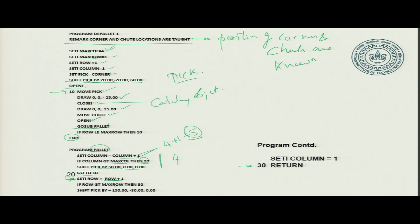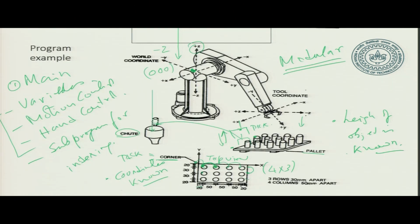Now, if the number of columns is not greater than max, then what it will do, it will shift the pick by minus 150, 30 and 0. So, from here it is going to shift the coordinates of pick to minus 150, 30 and 0. From here it comes to minus 150, which is right till here, and 30 is down here. So, it comes here, to the center of the object there.